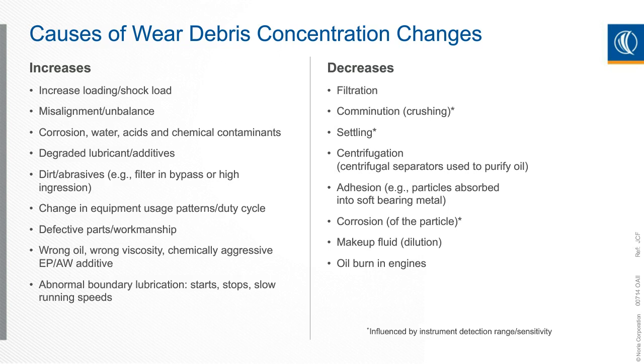The filter is actually pulling out all those contaminants. Maybe they're settling. So if you took a sample from higher in a reservoir, all that wear debris might be settling to the bottom compared to where a different sample might have been taken. So you need to be aware of what could potentially cause an increase in wear debris or a decrease, and then perform other tests to be able to confirm those results.